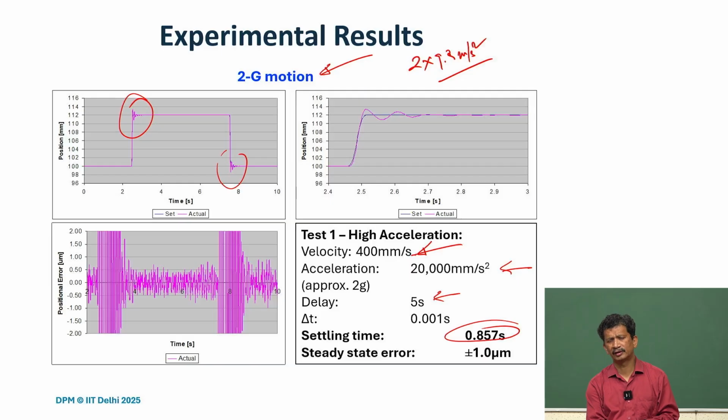Yes, I think damping is a big problem in this kind of system because the friction is not there. Friction is a big dampener, but it's not there, as it's required because we want better repeatability. But on the other hand, we don't have enough damping. So then we have to introduce damping, either electrical damping or by other means, so that we can get rid of these vibrations and it can settle easily. So, simple PID control, but these days one can use very advanced controllers, and a steady-state error of the order of 1 micron we are able to achieve.